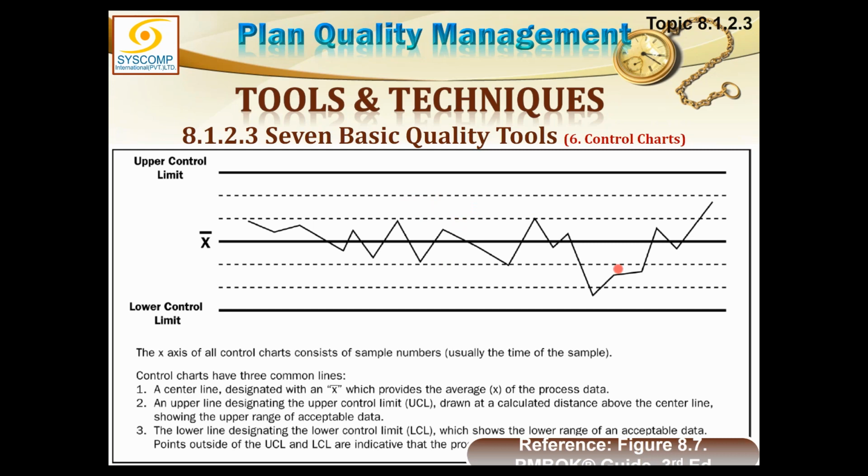No pattern should form here. It has to be random. So the standard rule here is the 7-point rule, meaning if 7 points occur simultaneously or consecutively on either the positive or negative side towards the upper or lower control limit, consecutive 7 points, that means there is soon to be a problem which will cause the start of rejection of your items.